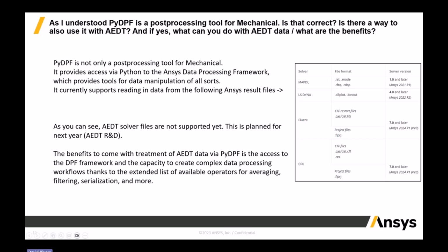Yes. All right. So first part of the question, as I understood, PyDPF is a post-processing tool for mechanical. Well, again, it depends on what you mean. The PyDPF libraries provide access to DPF, the Ansys data processing framework. And so in that sense, yes, it does enable you to do some post-processing on, let's say, mechanical result files. You can see on the right, I put the list of supported file formats for now. So we have MAPDL file formats, LS-DYNA, but we also have some Fluent and CFX file formats. Also be aware that, as Pierre mentioned at the very beginning, it really depends on what you mean by mechanical.